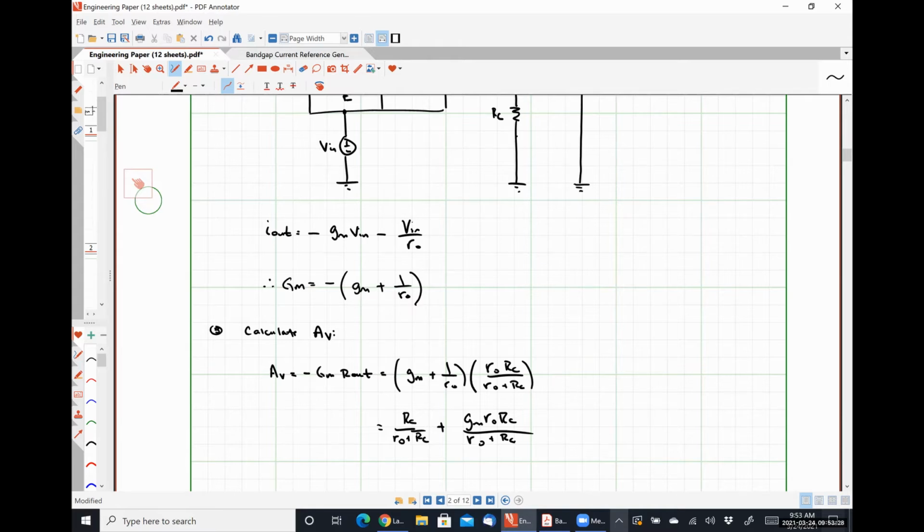So we can use this short circuit transconductance to calculate our small signal voltage gain. And one of the reasons why the book emphasizes this method so much is because it readily shows us that increasing our output resistance will have an effect of increasing the magnitude of our voltage gain every time. So this is a short and quick way to recognize that whatever we can do to boost our output impedance will give us a better amplifier with respect to gain characterization.